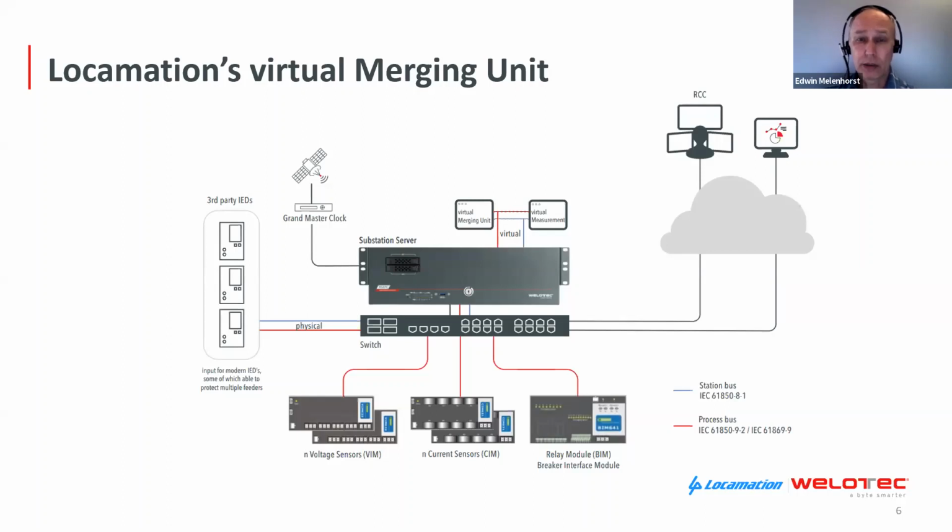You also see a BIM here, which is the breaker interface module. This interface module has several digital IOs for controlling breakers and monitoring breaker positions, for example. The next version of this product will also be based on 61850 communication, which will be GOOSE messaging.